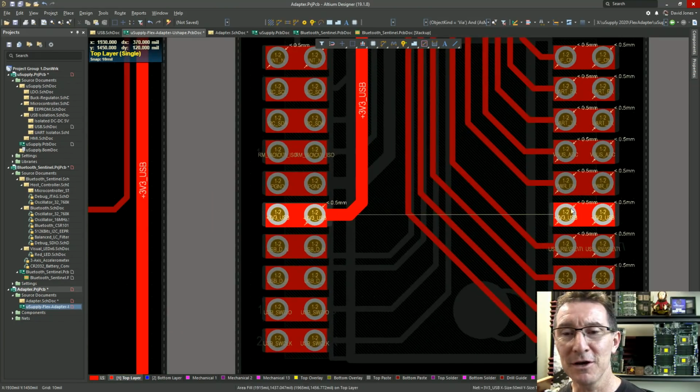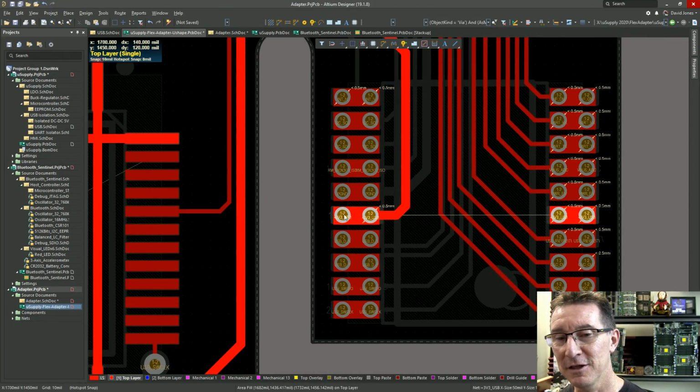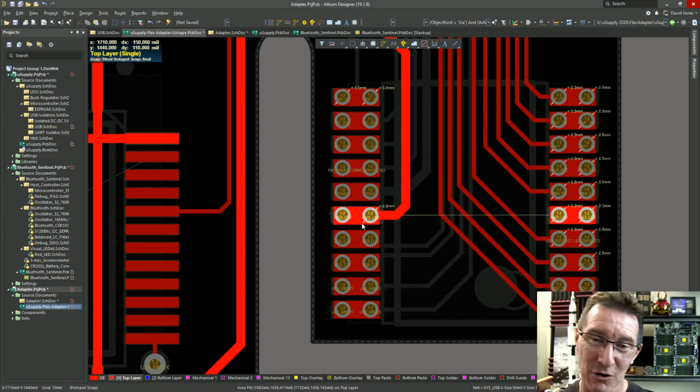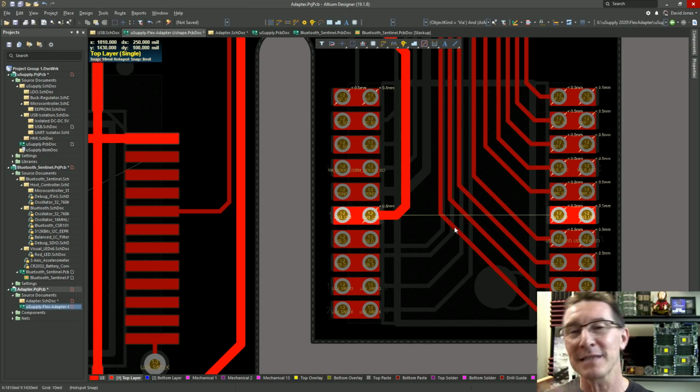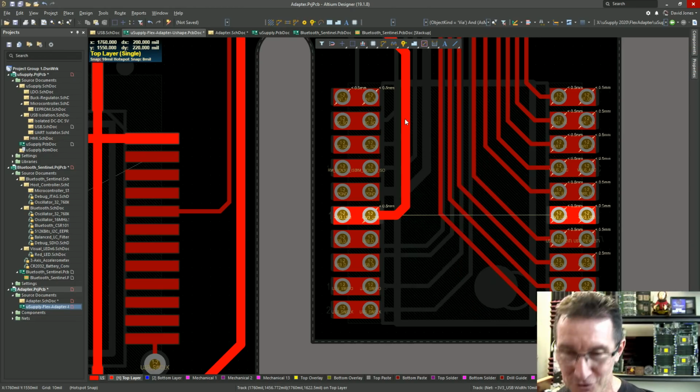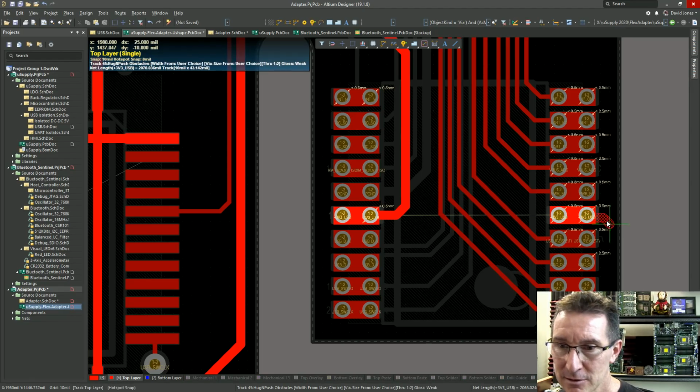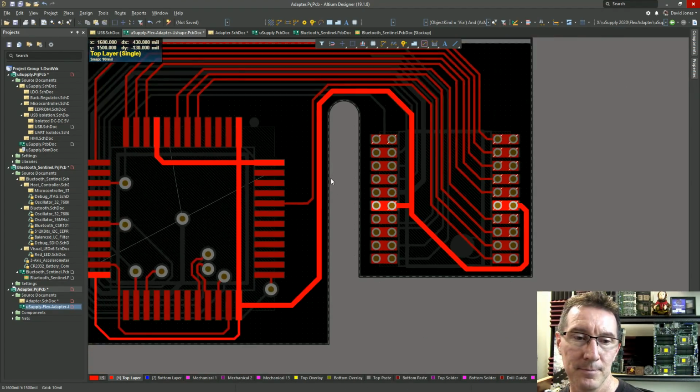And as it turns out, we don't actually have to connect this on top because this would already be connected on our board. So there's absolutely no reason to connect those two pads there. But just in case this one doesn't make connection and this one does when you're soldering, just for completeness and for design rule checking, of course, you would then get this across here like this. No worries. There we go.